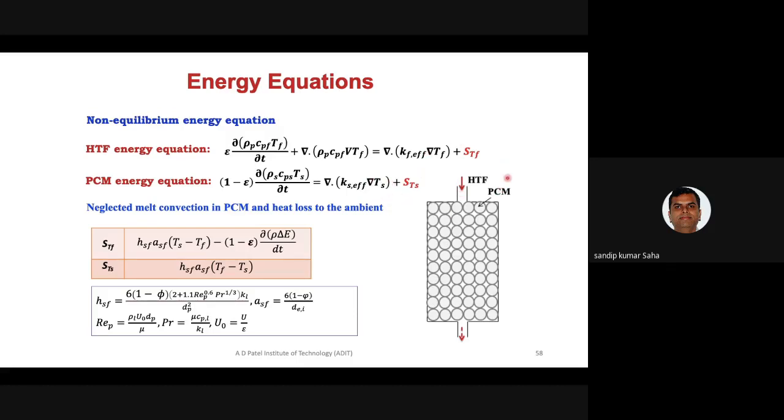Now, if anybody has used this module, he will be asked to give the interfacial heat transfer coefficient, and Fluent has certain definitions, like how they are unit-wise. So that unit you have to convert, basically, and you have to give this value.